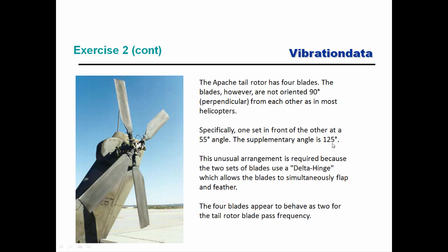So you might ask yourself also, why does the highest magnitude occur at the tail rotor rather than the main rotor in terms of blade passing frequencies? And a couple of reasons. The main rotors are churning up all this air. There's different wake turbulence, there's trailing vortices, and all these things going on. And we've got this tail rotor slicing into this churned up air. And also, there's something called a directivity pattern, and the main rotor is going to be roughly horizontal to the ground, or maybe even perfectly horizontal to the ground.